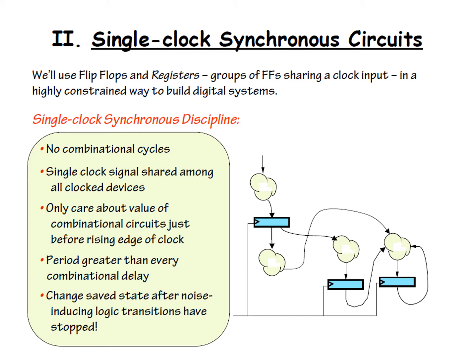For single clock synchronous circuit design, there's something you have to remember. The first is no combinational cycle, meaning any combinational logic has no feedback inside. Just the input goes in and the output goes out.